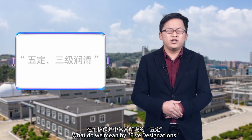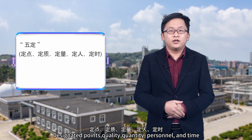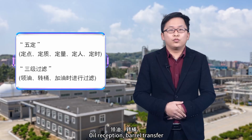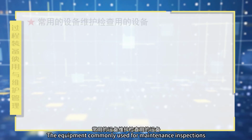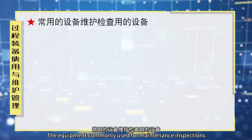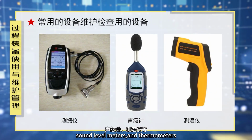What do we mean by 5 designations and 3-level filtration in maintenance? 5 designations: designated points, quality, quantity, personnel, and time. 3-level filtration: oil reception, barrel transfer, and oil addition filtration. The equipment commonly used for maintenance inspections includes vibration meters, sound level meters, and thermometers.